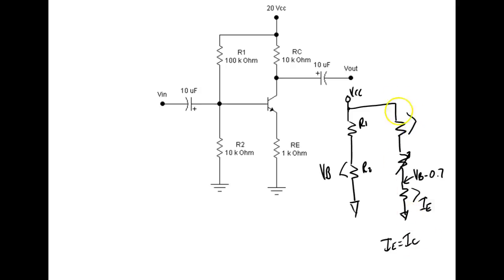So IE and IC are basically in series with each other. So what we do is we use that to calculate the RC. So we call this resistor generically, we call this RC, and we call this RE. And then we calculate voltage collector to emitter by what?